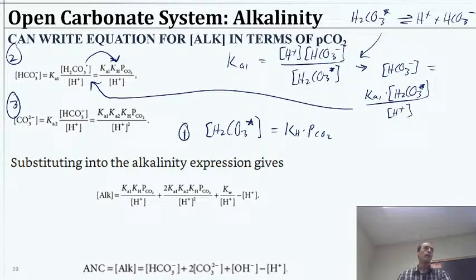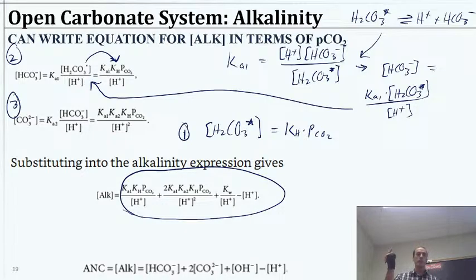And this time the slightly more complicated side, the kind that is pH dependent. And now we have a pH dependent function for our alkalinity. And so we can get that alkalinity equation in terms of only constants, pH, and the partial pressure of CO2. Okay? So now we can describe the entire carbonate system and solve lots of problems with it.